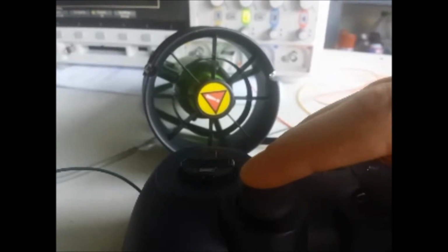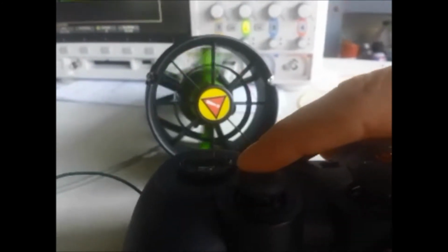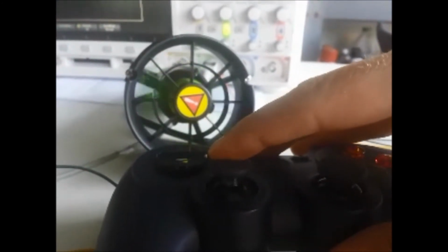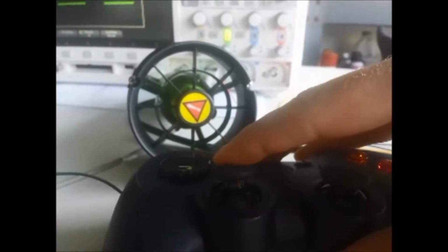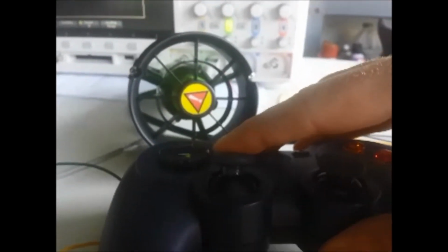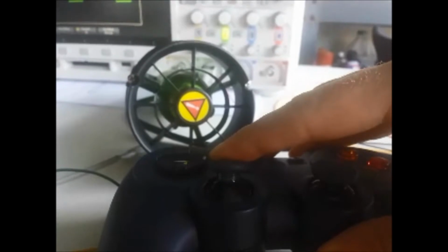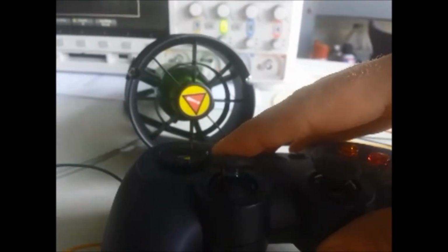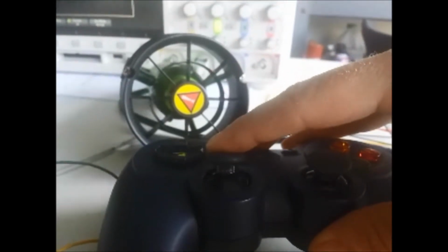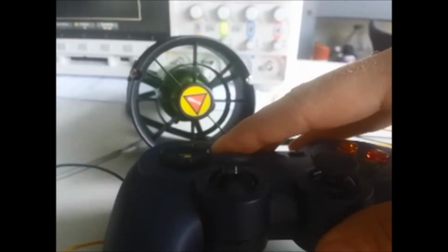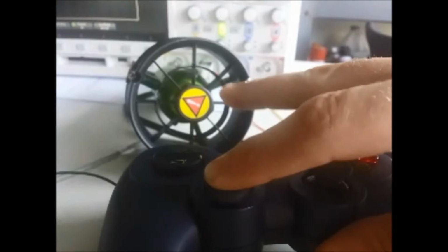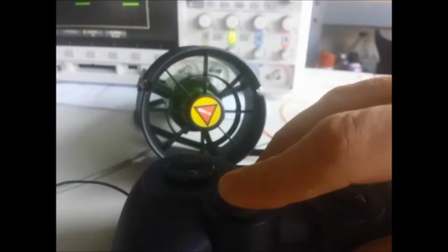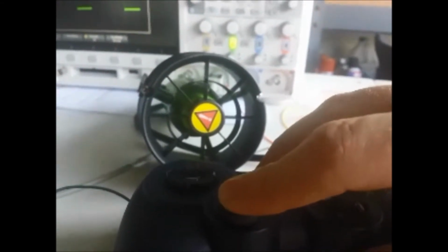I've also programmed the joystick to automatically ramp down if you go fast backwards, because if there's a big jerk, in other systems the more sensitive components would suffer EMI. So if I go reverse like that, it slowly ramps down and then goes back in reverse.